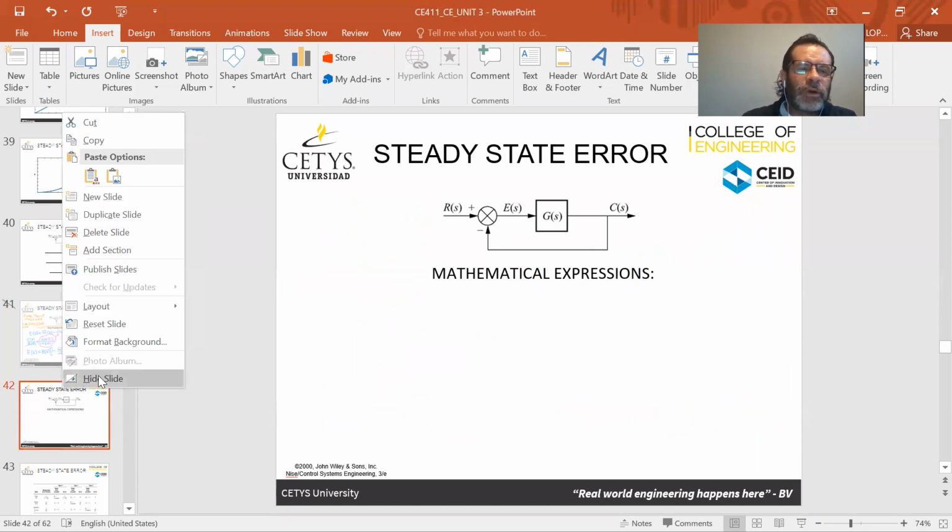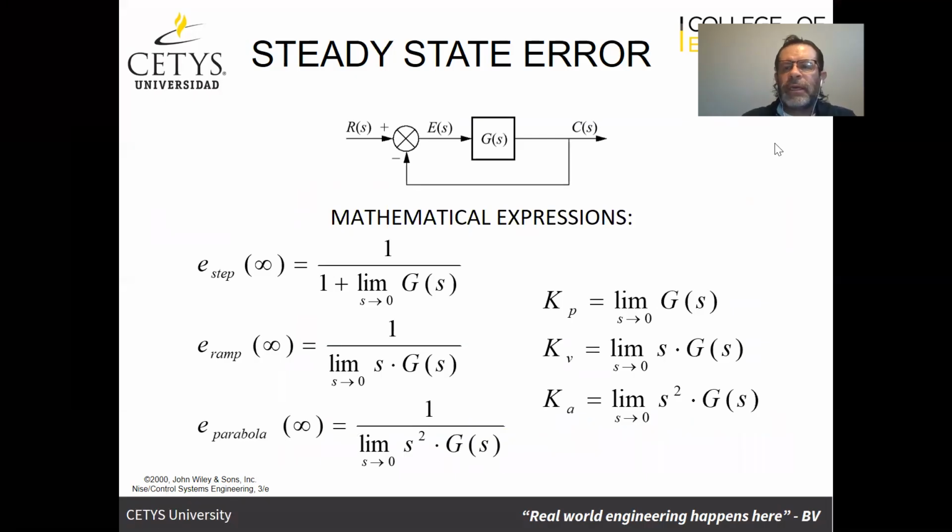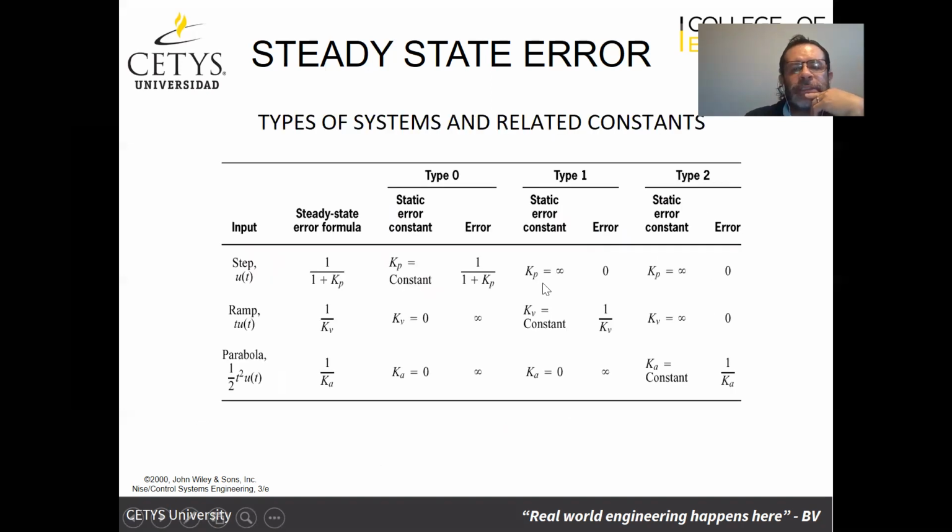The difference between one and the other is that it is of a different order. So we're going to classify systems according to their order, but in steady state, we're going to have a specific name for these, and they're going to be called the type of the system. And they're going to be with regards or relationship to the S that's in the denominator of G of S.